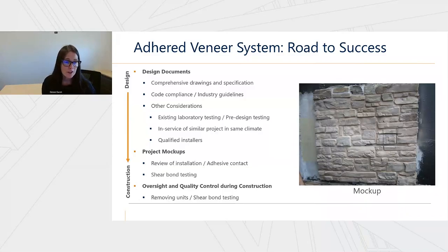Other considerations that may be included during design may include laboratory testing, pre-design testing, history of in-service of similar projects, similar climates, so that history of use. Also consideration for requiring qualified installers. Project mock-ups, we'll get into those, but this, in my opinion, is one of the most important steps to a successful project, is having those pre-construction mock-ups, and then during construction, making sure we have oversight and quality control.